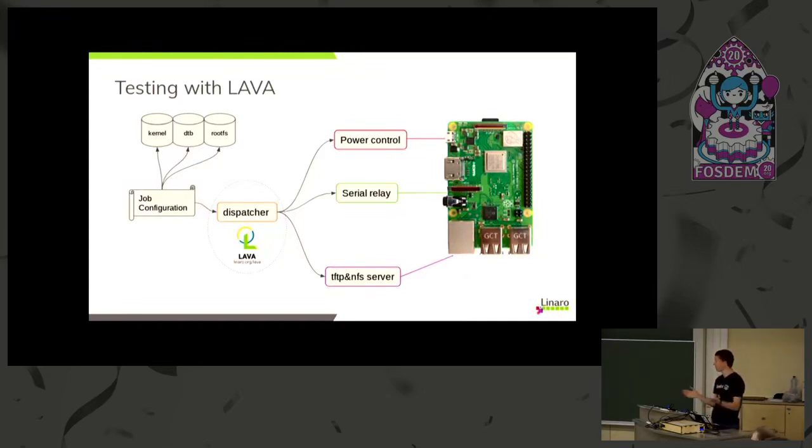You just give your URLs. I want to use U-Boot for booting because my board has U-Boot installed on it. And it will be a TFTP plus NFS boot. And I want to run the LTP test suite from this Git on this DUT, on this board.